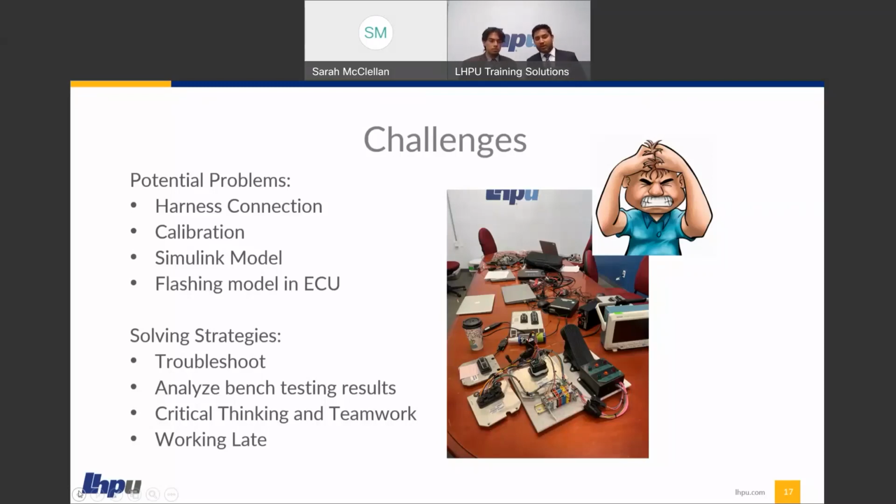The biggest blunder we made in the final step was flashing the model to the ECU. As I told earlier, there are two ECUs, the one with our model and the one with the CAN gateway model, which is already programmed. Instead of programming our model to ECU1, we programmed it to the CAN gateway model, which sends data to the VP44 on how much fuel needs to be injected. It was very hard to find the model for that ECU and reprogram it, so it took some time.